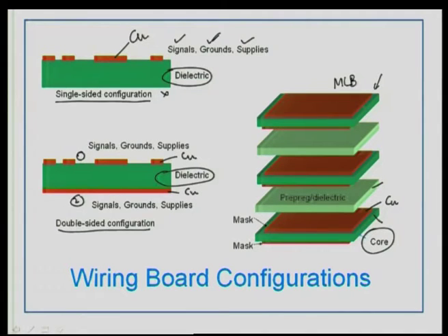So, we will end up with 2 plus 2 plus 2, 6 layers of copper separated by 2 dielectric layers that have been added later, and these are the core dielectric materials. We will talk about these structures later, but think about the difficulties in creating electrical layers for each of these. So, we will continue with more on CAD utilization for various wiring board configurations in the next class.